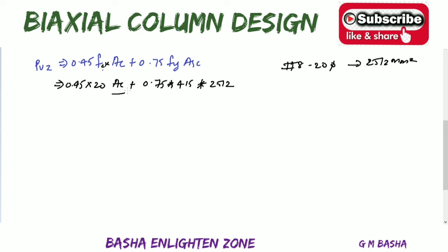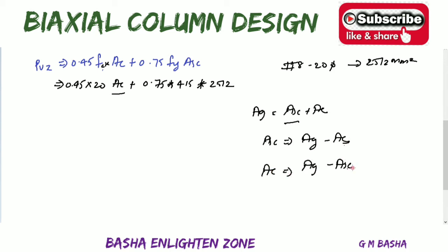Already I showed you so many times, in the overall gross cross sectional area, you have area of the steel plus area of the concrete. So we know area of the steel. So based on this one, area of the steel will be equal to gross cross sectional area minus AC. Sorry, AC will be equal to gross cross sectional area minus ASC. So we want the AC value.